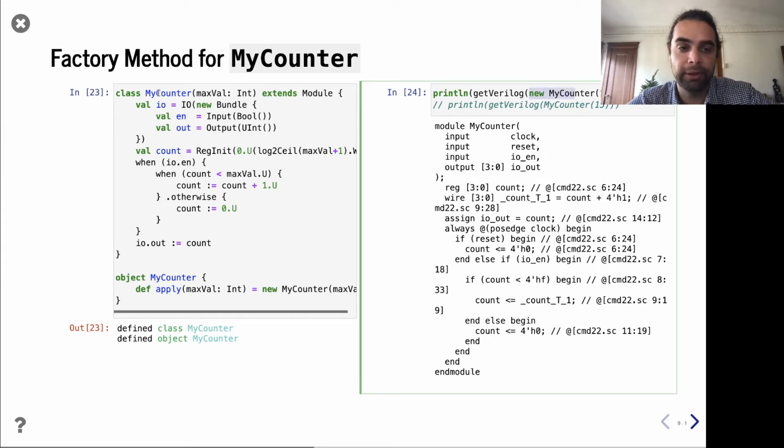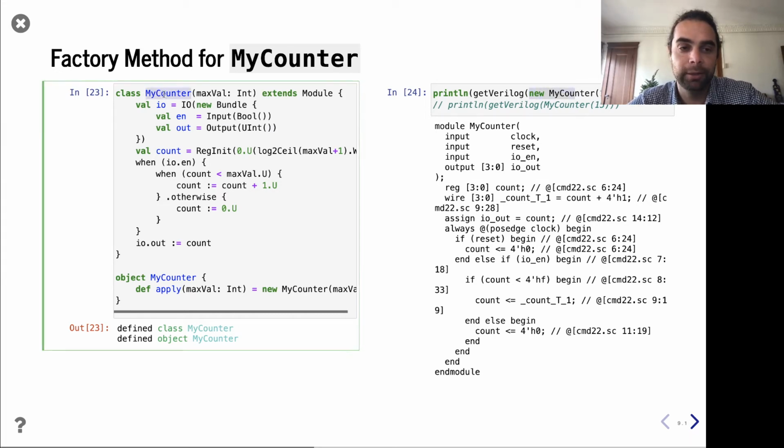Remember, if we look at our code again, our module is really a class we were defining, right? You keep defining all these modules, but we're actually just defining classes. These are the arguments to them. And we extend Module, right? So Scala is object-oriented. It has an inheritance system. By extending Module, we are bringing in a lot of stuff that makes us reasonable for Chisel.